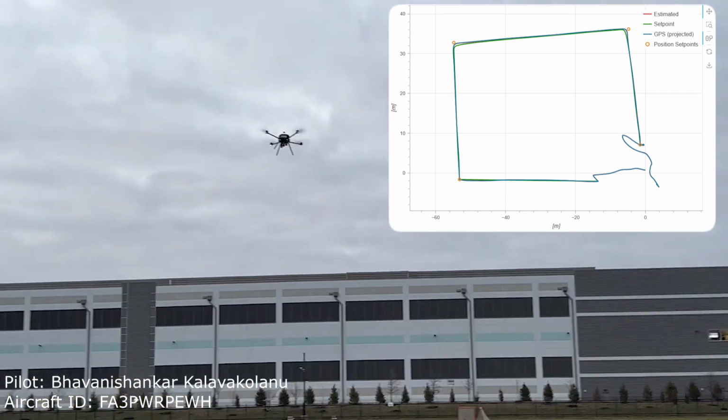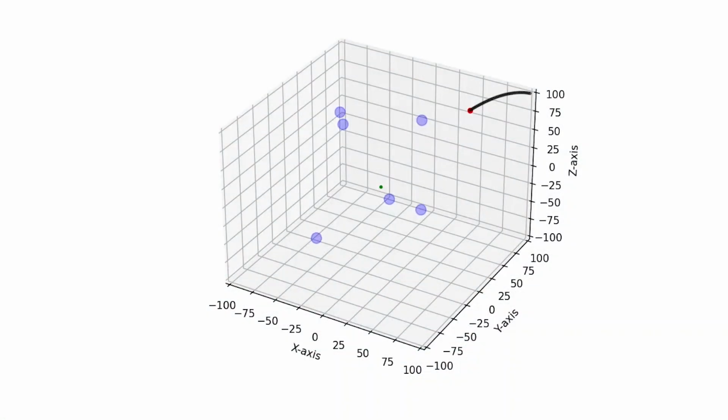For obstacle avoidance, a k-means clustering algorithm determines the relative position and size of obstacles at discrete time steps. Obstacle velocities are calculated by comparing the change in position across multiple time steps. The avoidance algorithm, called velocity obstacles, takes obstacle data as an input and outputs a maneuver. First, the algorithm uses obstacle data and tune parameters such as time horizon, distance horizon, and protected zone to determine the proper mode: restore, maintain, or avoid.